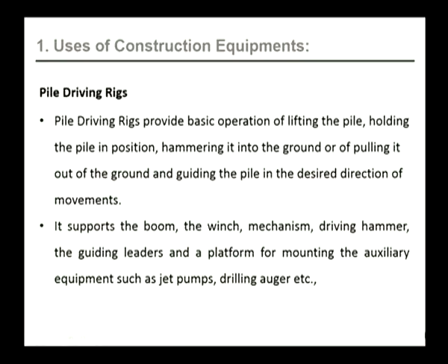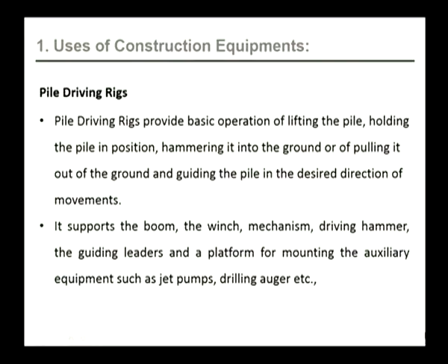We move on to pile driving rigs. Pile driving rigs are provided for the basic operations of lifting the pile, holding the pile in position, hammering it into the ground or pulling it out of the ground, and guiding the pile in the desired direction of movement. A pile driving rig is an instrument that takes the pile to a proper position as per the drawings and hammers it into the ground or pulls it out of the ground.